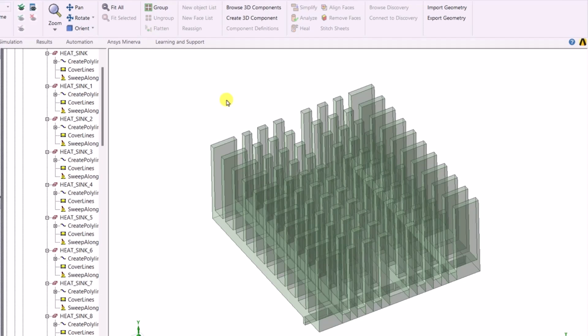However, it is not always necessary nor desirable to simplify all bodies to primitive shapes. Every model has its unique modeling objectives. Therefore, for each model, it is highly recommended to balance the time spent on CAD simplifications versus the time spent waiting for a high mesh count model to converge.